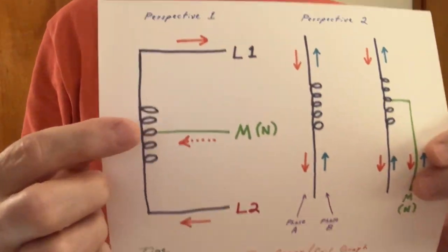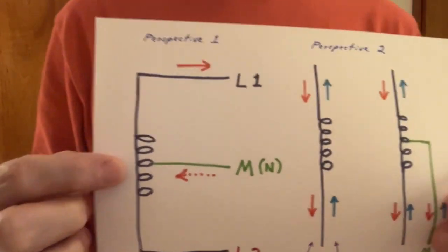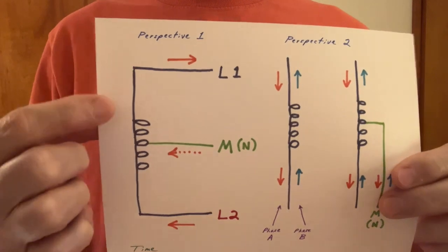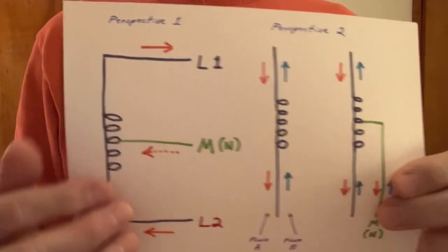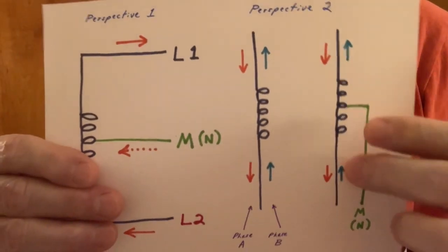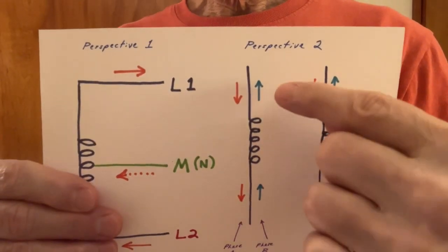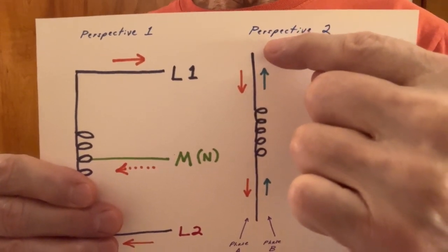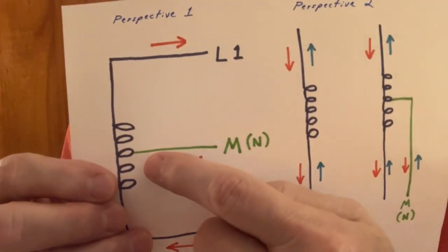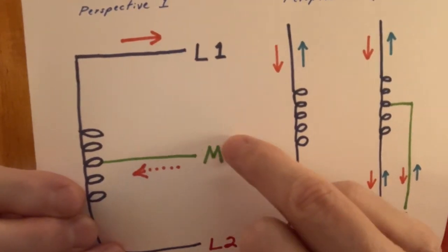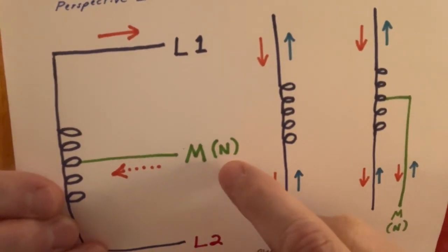And I'm thinking, oh, one coil, single cycle, all right? Because we imagine this because this is what we're told. We look up there on that pole, we see a transformer, and we see 3 conductors coming out. So we think we can have multiple items here. No, all you have is an illusion. You have one coil here. What you have is reference points. You have the end of this coil and you have the other end of this coil. And somebody decided, well, you know what? Let's stick something here right in the middle of that coil. We'll call it a neutral. I call it a median, but let's call it a neutral, right?